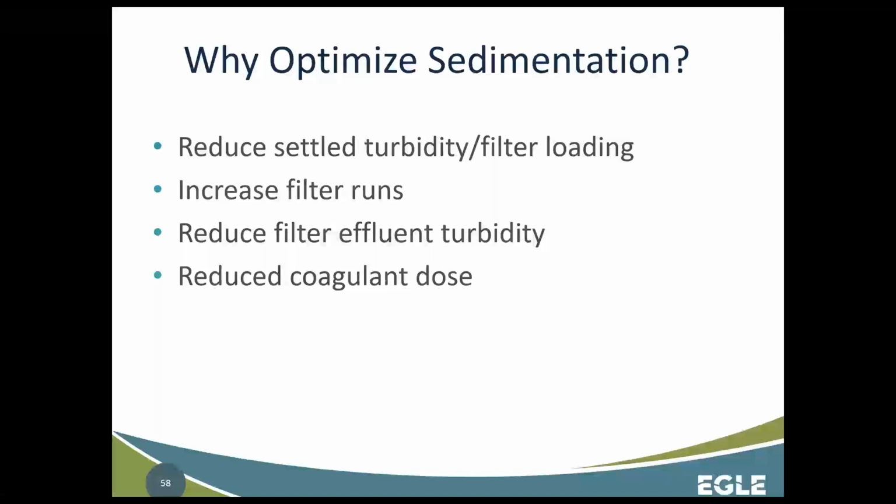And maybe that could all be rectified by adjusting a valve and forcing more of the flow into the second basin. Just because they're identical design doesn't necessarily mean that they're going to have identical performance, because the loading could be different between the two units. And you might not know that unless you were evaluating both of them. Of course, if you have a continuous turbidimeter that's data logging, that's going to provide you with a lot more resolution than grabbing grab samples occasionally throughout a shift.